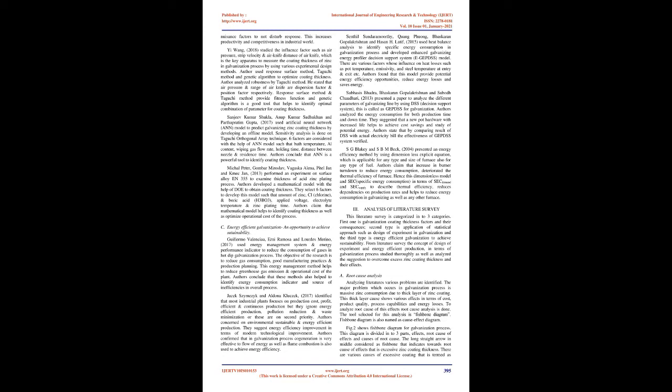Authors found that when Al was less than 20%, coating was under control, and when Al was 35 to 90%, then the process changes from galvanizing to aluminizing. There were two types of dross found. Authors claim that both are insoluble in the zinc bath due to higher melting point within the operating temperature.